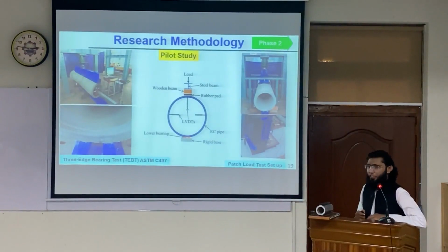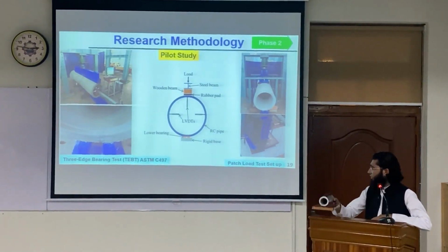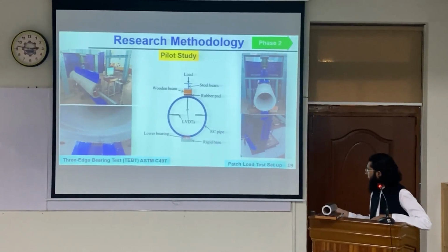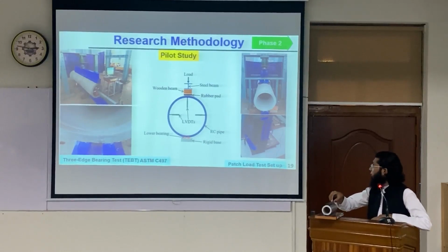So this is the test conducted on the pilot study, the 3-edge bearing test. This is the physical model of the test: an upper bearing and 2 lower bearings, and the pipe is loaded from the top. The other test is a modified form of the 3-edge bearing test, with the difference that the load is applied at the mid-length of the pipe instead of as a uniformly distributed load over the pipe.